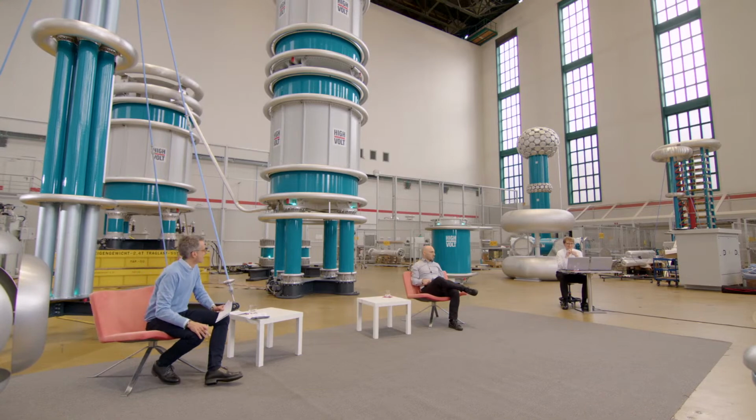Because if you want to reach this high sensitivity, which we talked about, you really have to couple at least to every link box, which is at maximum, as far as we know, 12 kilometers away. There you have to mount appropriate measuring devices to have the high sensitivity for this 12 kilometers. But if you really want to locate a failure after a breakdown, then you have a very big signal, of course.